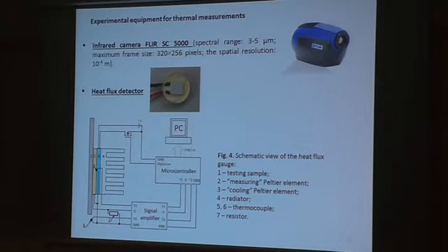It could be quite simple: one Peltier, a big cooling setup, and you can measure the heat flux. You can measure the electrical current in the Peltier element and calibrate it according to the heat flux moving through it. We tried to do it, and the first result wasn't satisfactory, and finally we have used two Peltier elements, one for measurements, the second an active system of cooling.